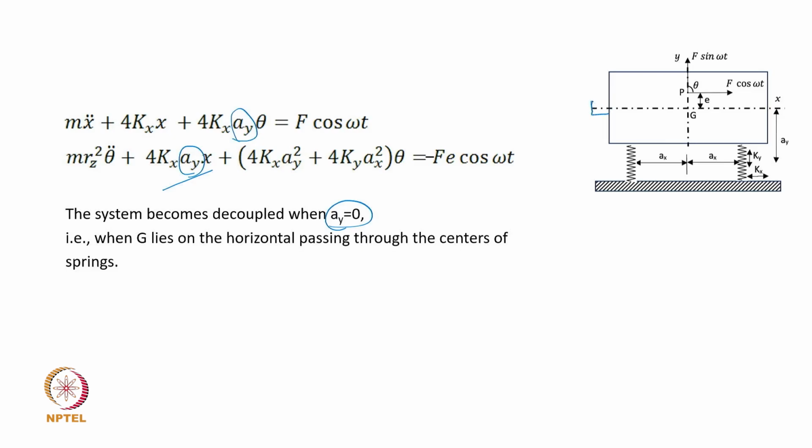And that will happen if I somehow support this condenser unit over here instead of supporting at the base. Maybe I can show this spring to be here, so that the center of the spring is not even having this much offset.